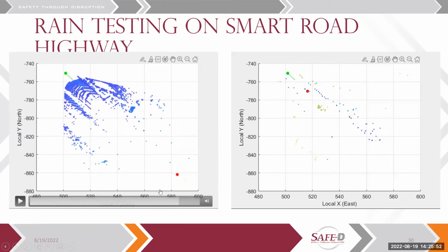It could be perhaps the time of flight effect for the LiDAR. It's going through a different medium than air, and so it might change those time of flight calculations. And since you're dealing with the speed of light, any minor difference there is going to have a big offset.